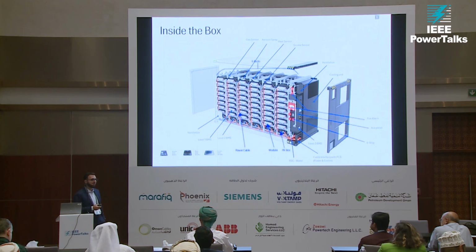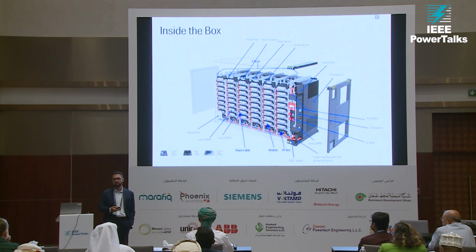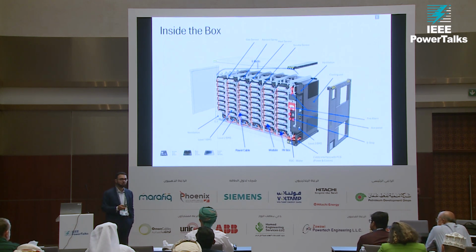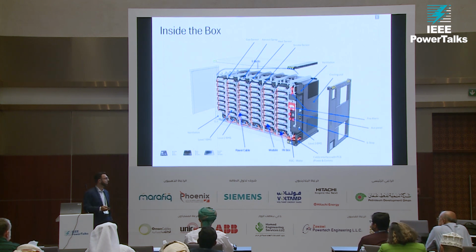The industry is really evolving so fast. I remember my first container that I installed was a 40-foot container that had less than 600 kilowatt hours in it. The system that we installed more recently, in a 20-foot container, has about 6 megawatt hours. It's a massive development. These typically weigh around 40 metric tons, so they're pretty heavy. And that's why we went from a 40-foot container to a 20-foot container, just from a weight restriction standpoint, to be able to ship them on ships and also on road shipments as well.